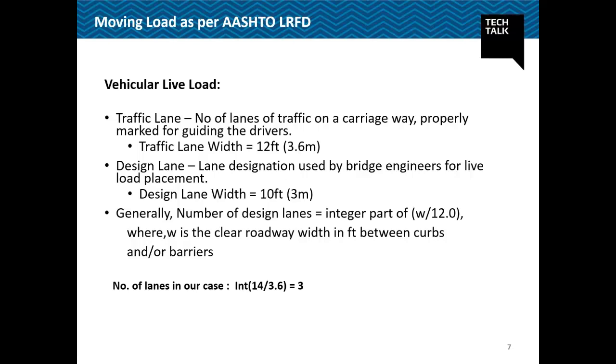number of lanes, and for design lane, the lane width we are going to take as 10 feet, which is 3 meters. Okay, so in our case, the total carriageway width is 14 meters. Once I divide it by 3.6, I get the integer part as 3. So for our case, the number of lanes will be 3.